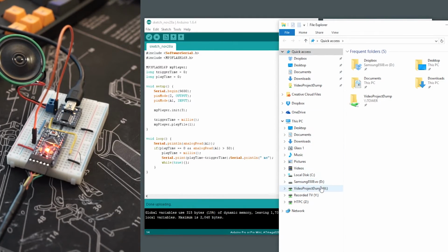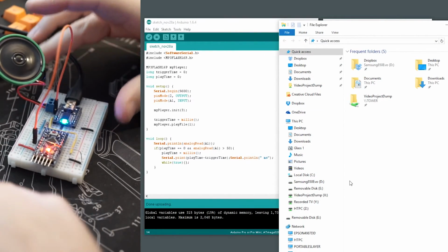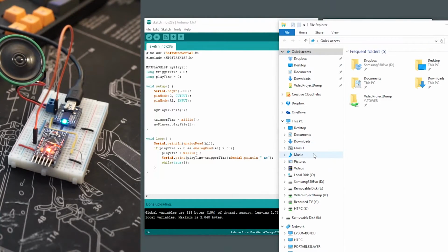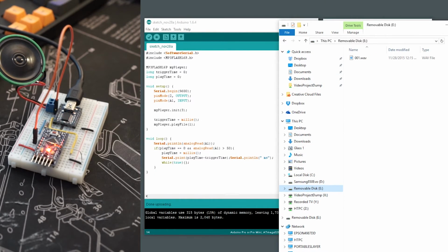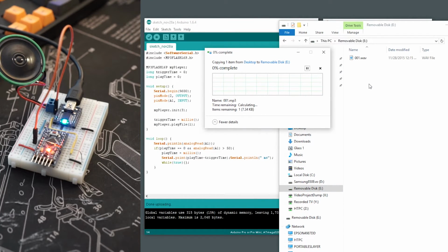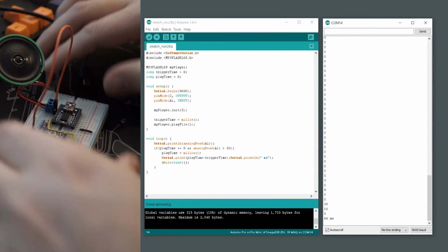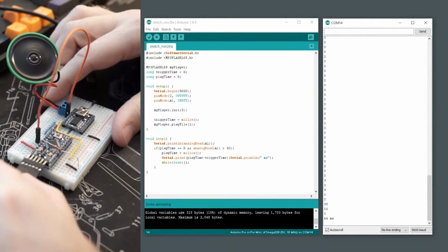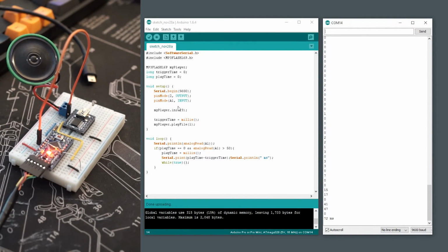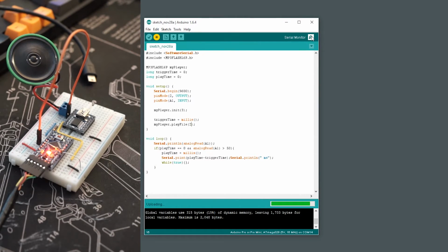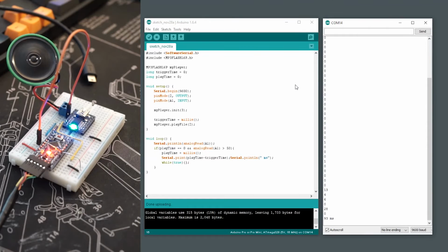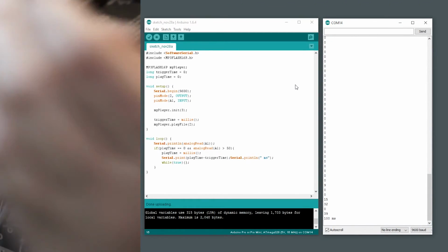And with those results in, I connect the device and upload the MP3 file. Because I'm communicating over serial this time, I can upload the file as 002.mp3 and modify the code to alternate between playing the WAV and the MP3 file. Another advantage of using the library. So I re-upload the code now with the play file changed to play file number 2, and reset the Arduino 3 times to get my results.